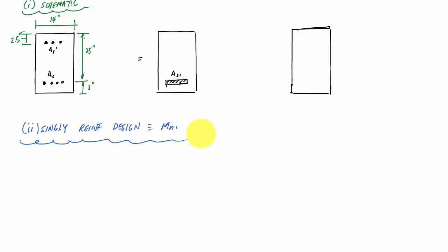There's a temptation sometimes to guess a rho associated with 0.005. The reason that is problematic is that rho of 0.005 is associated with an area of steel As1, and when we select the actual bars from As required, we're going to be rounding up and adding more steel than the target reinforcement ratio.